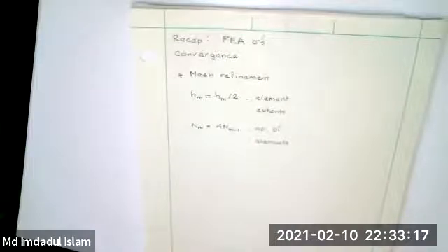Anyway, let me recap how you check finite element stresses for convergence. This assumes that you've got a working code that's already been verified, which for all the standard codes is a very reasonable assumption for these sort of elements. There are some tricky elements where that's not necessarily true for major codes like ANSYS and Abaqus, but these basic elements, and their 3D counterparts, are the ones that are most used in practice. These elements have been fully verified.